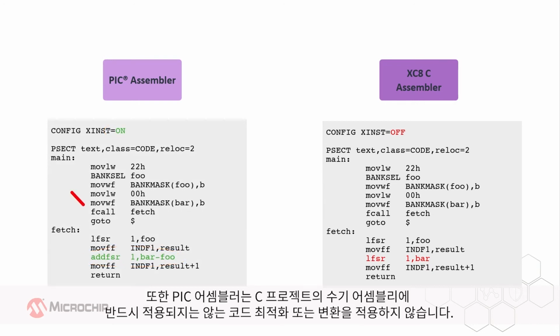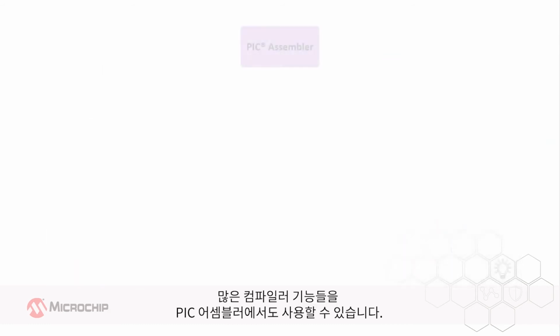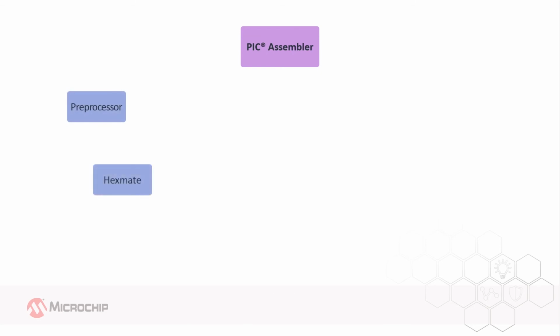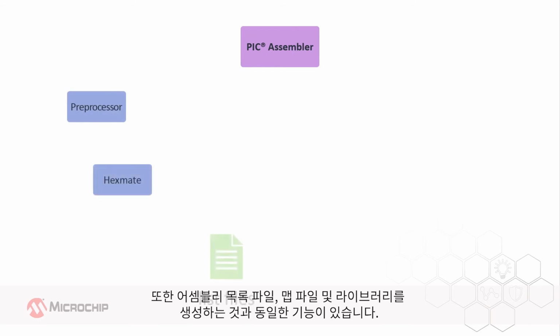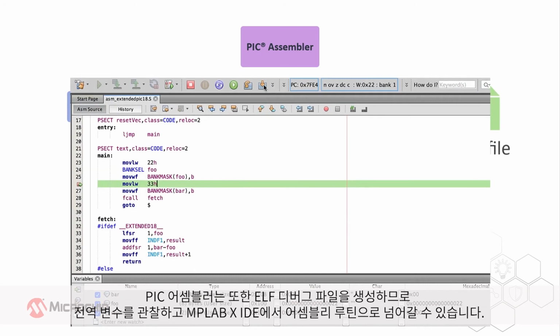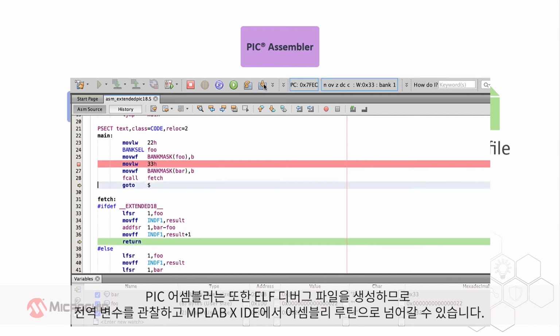In addition, the PIC assembler does not apply any code optimizations or transformations, which isn't necessarily true for handwritten assembly in C projects. There are many compiler features that are also available in the PIC assembler, such as a C preprocessor and utilities like Hexmate. Plus, it has the same ability to generate assembly list files, map files, and libraries. The PIC assembler also produces an ELF debug file, so you can watch global variables and step over and into assembly routines in the MPLAB X IDE.